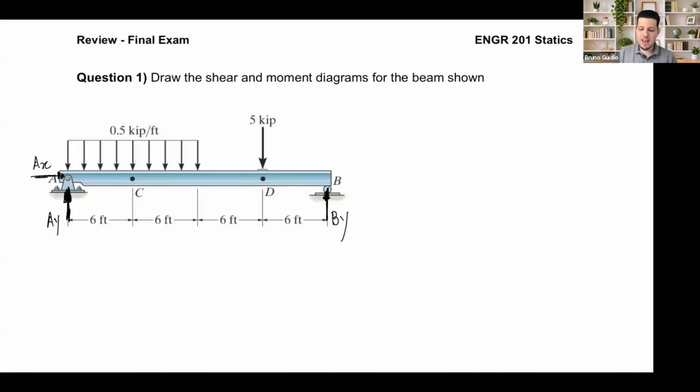On the left we have this pin support. On the right we have this roller support. So what kind of reactions? BY, AX, AY.